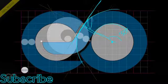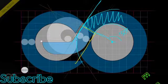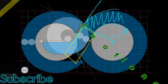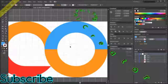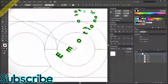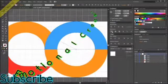So this is going to be a completely different section, and then once I have that portion cut out, I'm going to add this portion extra, right? So this portion is going to be an extra here. So this entire section which you see here is going to be an addition. So to get that one, I'm going to select this line and this. If you're unable to select it, just go into Control Y, the outline mode, and you can select it. And I'm going to go ahead and divide.